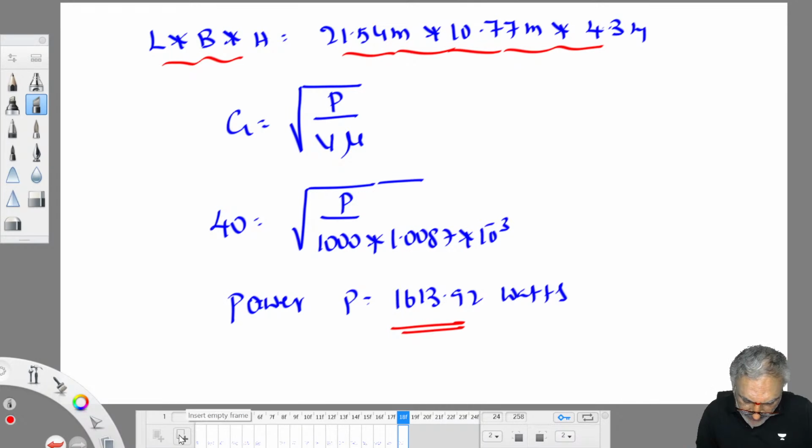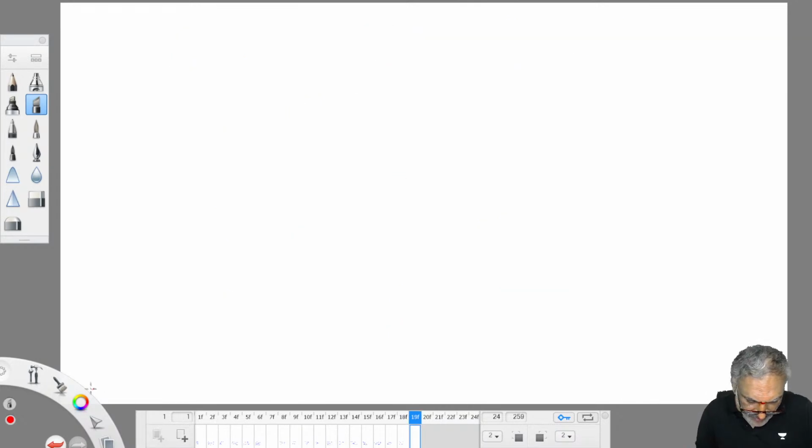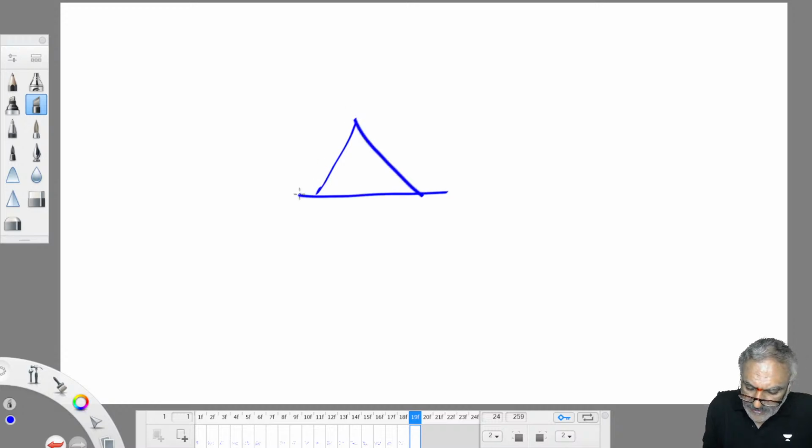Paddle design is also there, but for paddle design we will not go into that much depth. Paddle design means generally the size of the paddles. So the paddle is rotating inside. This is a flocculator. The bed of a flocculator is a supporting mechanism for the paddle. This is a shaft. So this will be rotating.